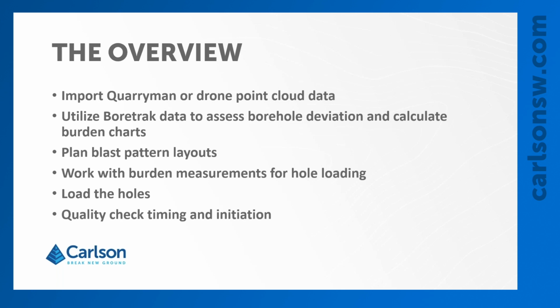So you can assess the borehole deviation and calculate your burden charts. You can create blast pattern layouts. You can work with your burden measurements for hole loading. You can then load the holes and quality check the timing and the initiation. So all of this happens within the software itself using the different modules within the BlastOps software.